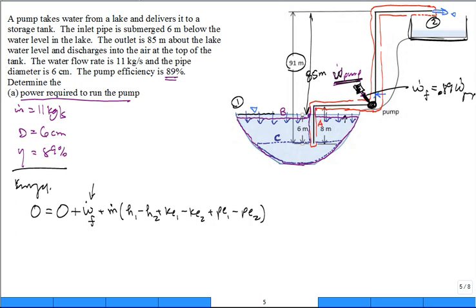All right, so what about if it's lake water, then the enthalpy, H, for an incompressible substance, H1 minus H2. Can I replace it by C sub P, T1 minus T2? Did I talk about the temperature change of the water? Negligible. So the change in H is 0.